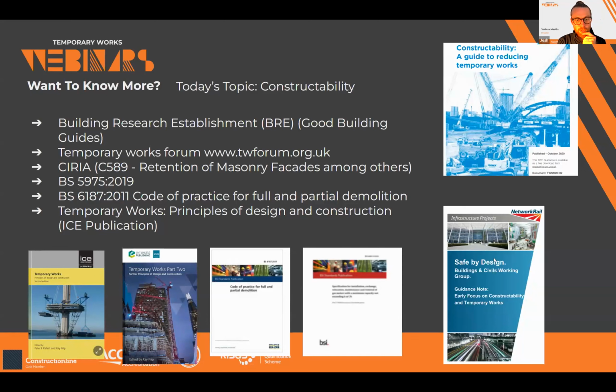In terms of temporary works, there's a couple of good guides that I've listed on there. So there's Temporary Works in Principles, the yellow one on the left. There's a new one, which is part 2, which I've put in there as well, published by the ICE. There's BS 6187 about demolition, partial and full demolition, which I mentioned earlier, as well as BS 5975, which is the temporary works British standard. But there's lots of really good information out there for you to see.